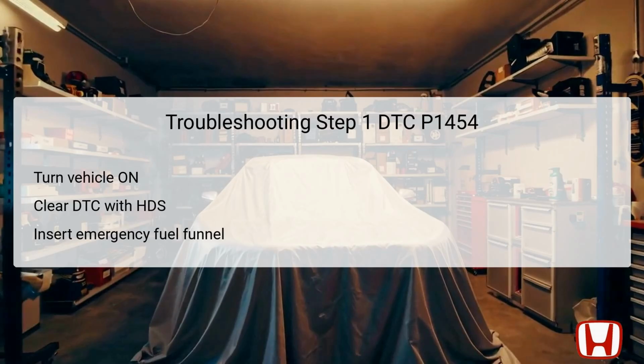After this waiting period, it is crucial to check specific parameter values with the HDS to determine if the issue persists. For the second step in troubleshooting DTC P1454, first turn the vehicle to the off or lock mode, ensuring the system resets properly. Afterward, carefully remove the emergency fuel funnel from the fuel filler neck, as this component is no longer necessary for testing.